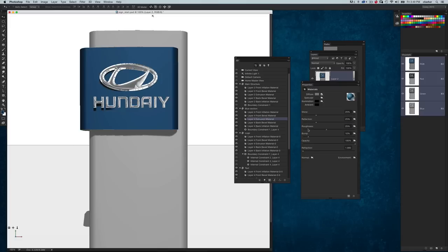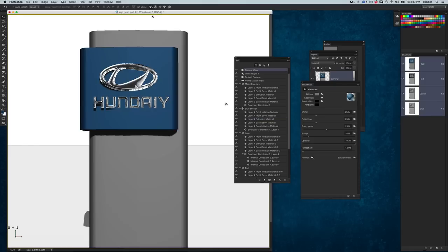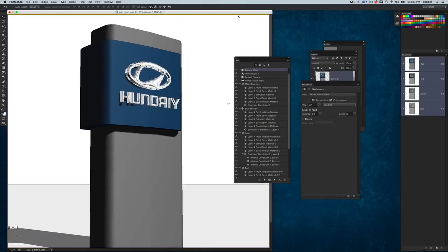When you have the roughness at 0, it's going to reflect pretty much at 100%, almost like a mirrored reflection. But increasing the roughness smooths it out and gives it a much softer reflection. The higher you go, the softer the reflection gets. So if you want that kind of faded reflection, that's what that roughness setting is for. In this case, that's what I want.